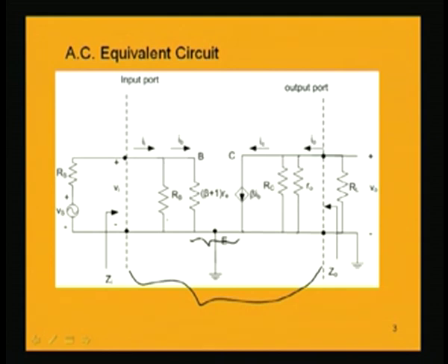One part is through this resistance RB, and the other part is through this resistance beta plus 1 RE. And the current source at the output, IC, is equal to beta times IB, and the current flows in this direction, going to the output side. The input base current comes and flows like this.